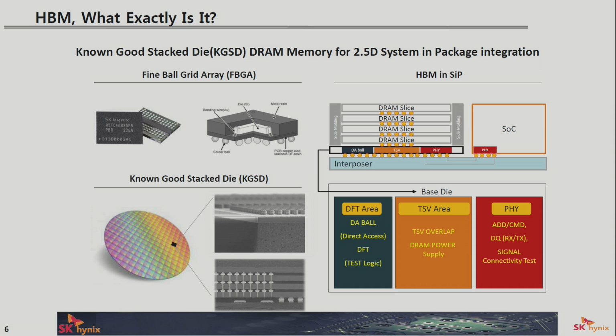HBM itself is really agnostic to the interposer technology, but there are reasons why we see in the industry that all commercialized programs with HBM in 2.5D integration are using silicon interposer. We do see alternative solutions such as organic interposer and organic substrates with embedded organic interposer becoming commercially viable within the next 1 to 2 years. So that's exciting for the overall HBM ecosystem.